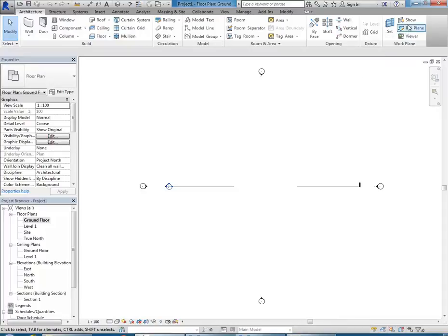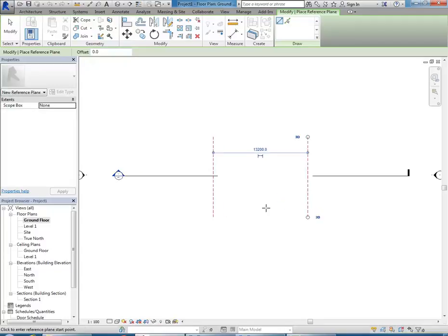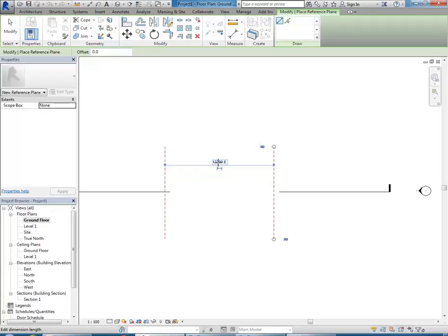And so then with reference planes, it's always a good idea to set out those main dimensions. And so I'm just going to draw a couple of vertical reference planes to set out the horizontal measurement between them, and make that 11500. And I'm just drawing reference planes. So then going the other way, crossing over those to draw two horizontal.